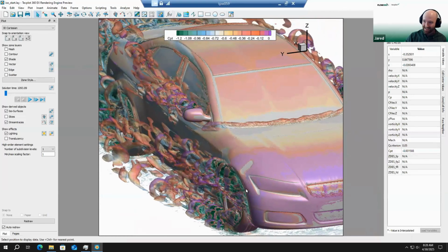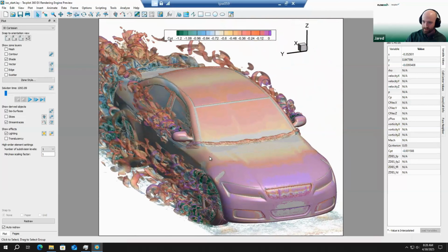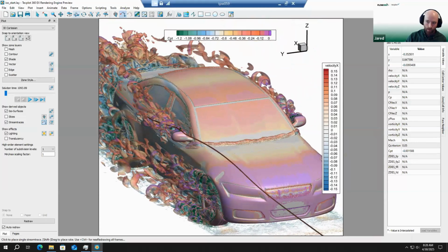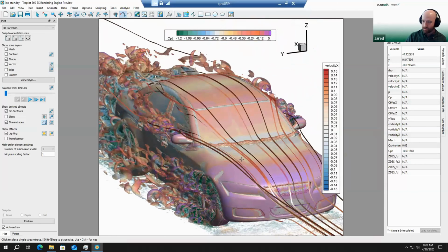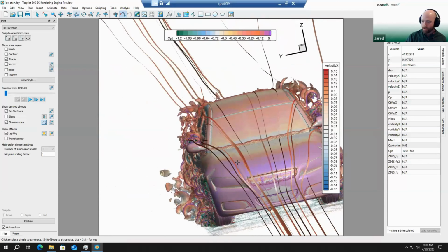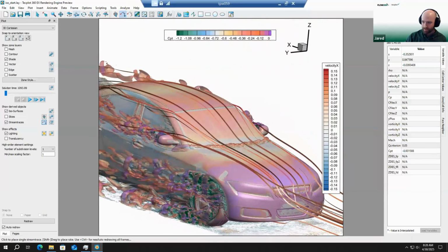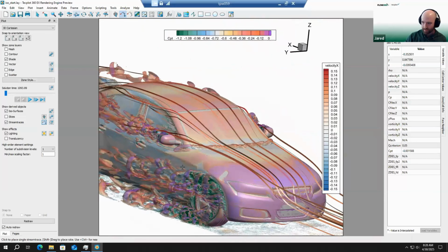And then if we wanted to add some additional plot elements to this, I've already prepped the stream trace tool here, but I can click this add stream traces, and wherever I left click, we're going to get a little bit of a load operation because again, we're pulling and loading the subzones as needed for the plot, but it doesn't take too long to then plot these stream traces. I could click and drag. Let's add it at the wake here. It'll take a little bit longer as we're loading more and more there and as we're plotting more, but it doesn't take too long. And then we can see a little bit more information about the flow in our plot. And again, still runs very smoothly as we're manipulating the plot.